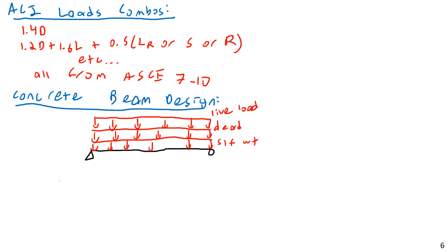We analyze things as true tension members, where you have only tensile load applied. But if you think about statics or mechanics of materials, intellectually you can realize that there is no way you can ever have a pure tension member, or at least you can't have a tension member made of anything that has mass, anything that has weight. Because if a tension member is actually made of matter, as it's hanging there in the air, it's going to have its own self-weight, and that's going to introduce some sort of bending to it.